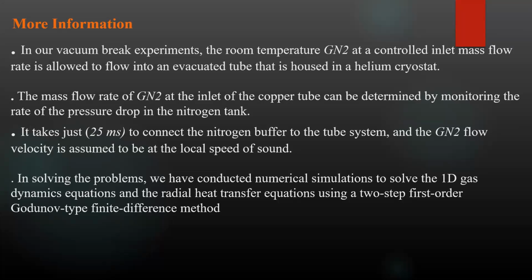It takes just 25 milliseconds to connect the nitrogen buffer to the tube system, and the nitrogen gas flow velocity is assumed to be at the local speed of sound. To solve the problem, we have conducted a numerical simulation to solve the 1D gas dynamics equations and the radial heat transfer equations using a two-step first-order Godunov-type finite difference method.